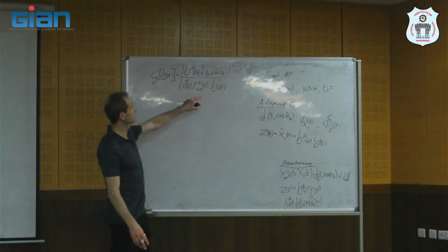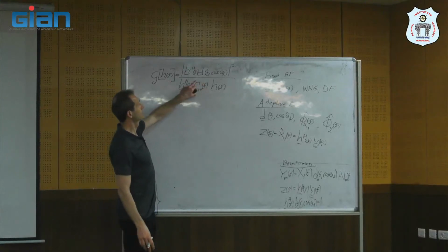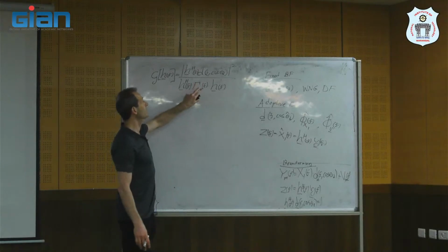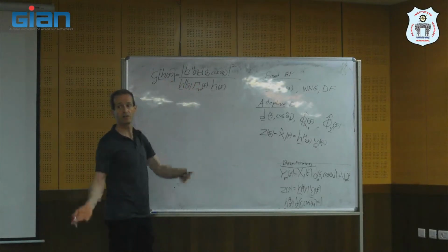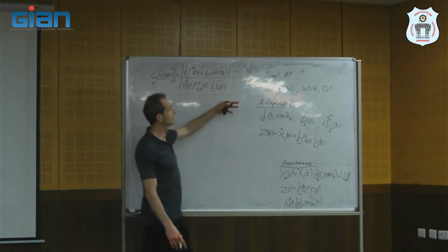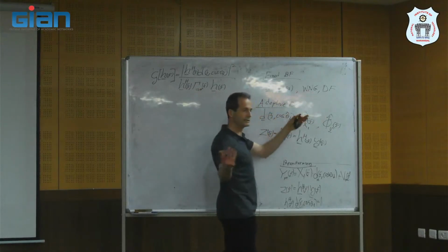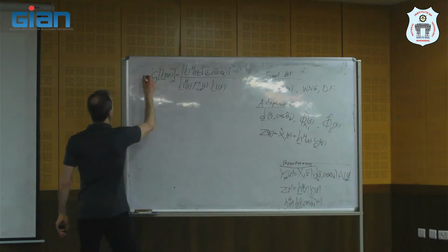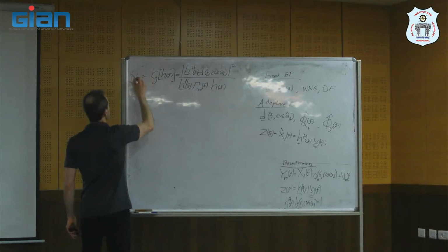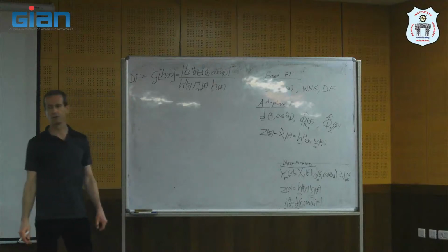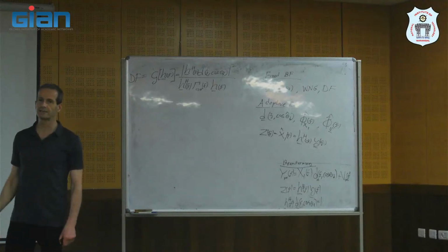Because here we put the normalized correlation matrix of diffuse noise. If we put another one, it's the array gain for that environment. But for a fixed beamformer, we need to assume a certain noise field, either this or a combination or whatever. So if we use this, we call it the directivity factor, because here we have the normalized correlation matrix of diffuse noise.